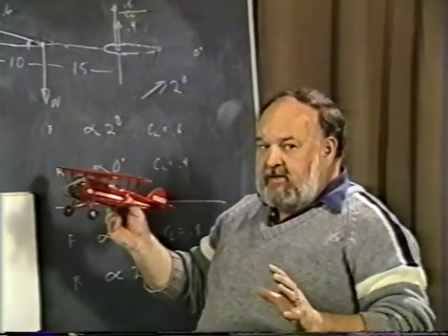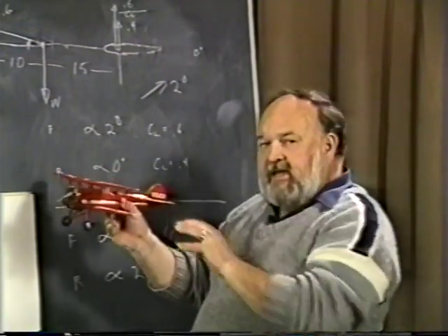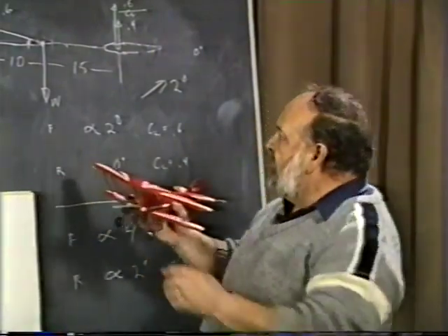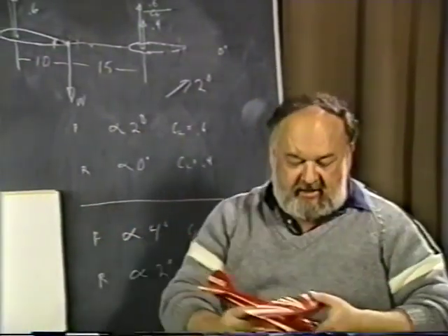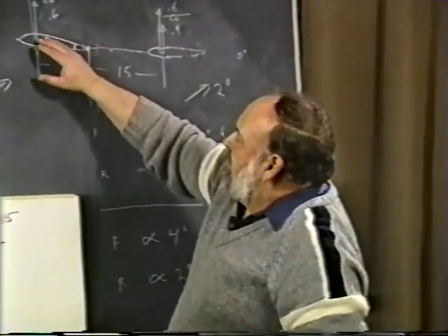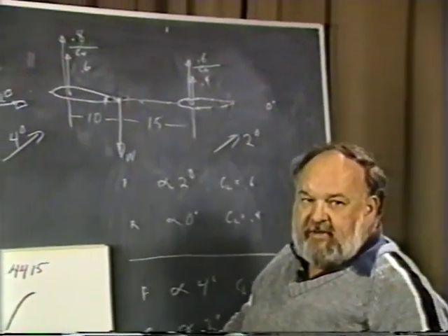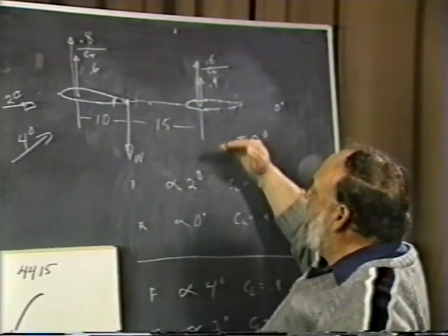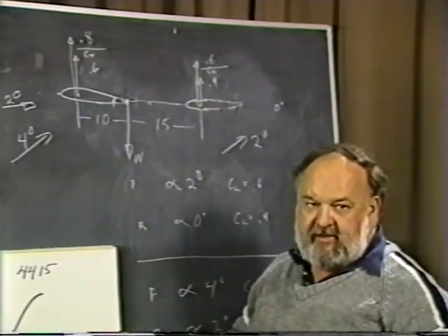Now, in fact, you could go so far as to say, let's have the wing flying along and the tail at an angle of attack that is producing no lift on it, none whatsoever. Well, now the balance point has to be right under the quarter chord of the wing. And in that case, it's very easy to see that if the weight is totally under there, the rear section is lifting nothing, but as soon as it gets any form of a change of angle of attack, whether up or down, it will immediately try to restore the wing up or down in the same particular way.